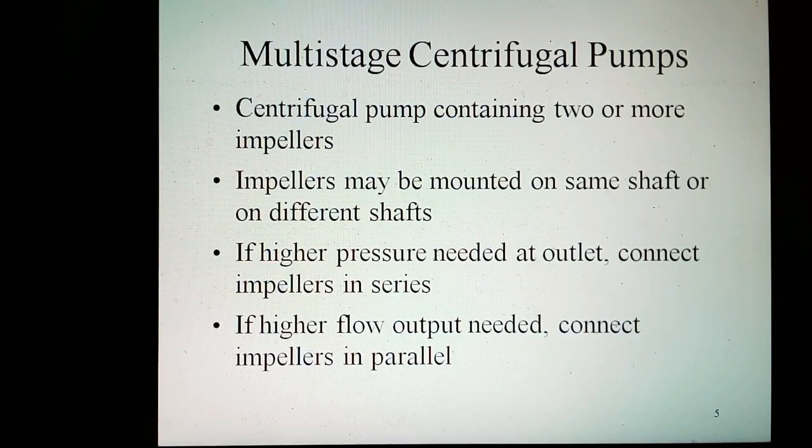Multi-stage centrifugal pumps. A centrifugal pump containing two or more impellers is called a multi-stage centrifugal pump. The impellers may be mounted on the same shaft or on different shafts. If we need higher pressure at the outlet, we can connect impellers in series. If we need a higher flow output, we can connect impellers in parallel. All energy added to the fluid comes from the power of the electric or other motor driving the impeller.